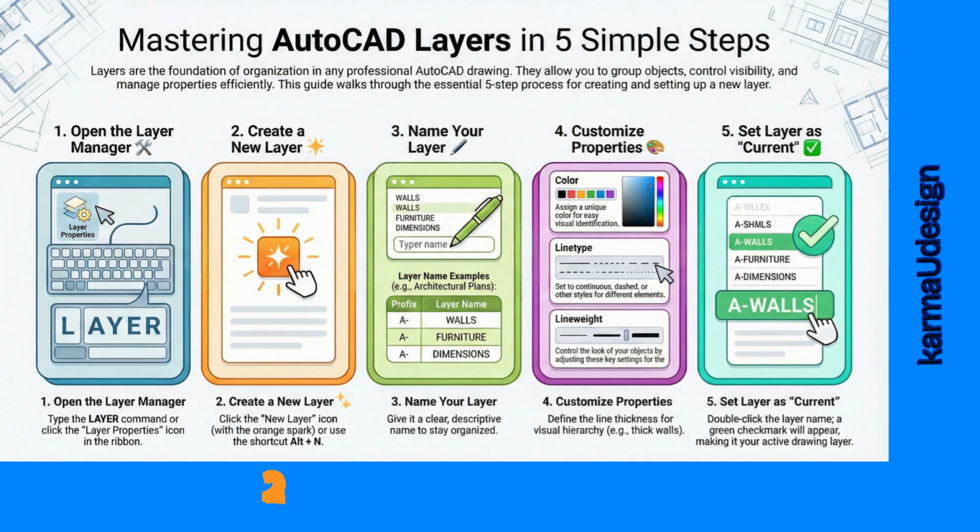So once we have that blank, unclassified placeholder, we immediately run into this critical strategic issue of semantics, which is step 3, naming and organizing the layers clearly. Yes. This is where most drawings fail when they start to scale up. This is arguably the most vital step for long-term collaboration, for auditing, for everything. If you look at a project with 50 layers, and 20 of them are named line, red, layer 1 copy. Old walls. Old walls, exactly. The file becomes instantly unmanageable, especially for someone who didn't create it.